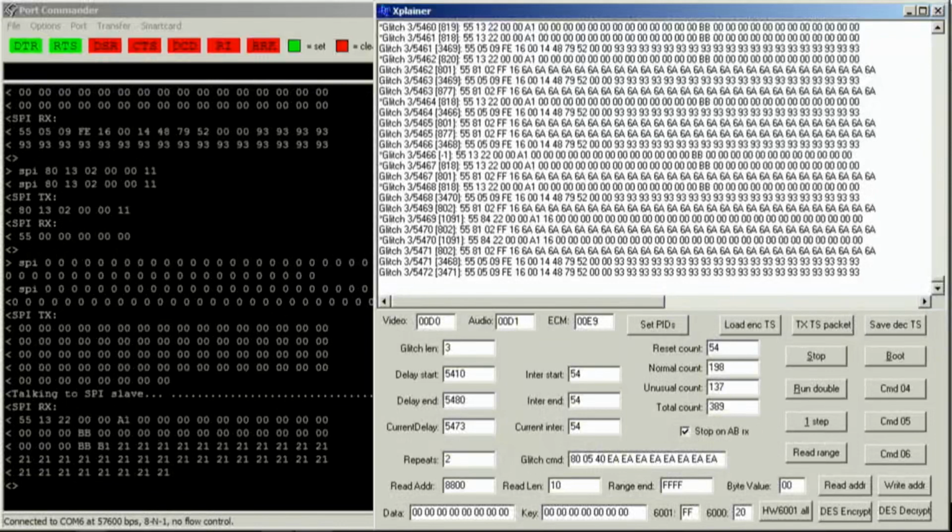There are specific addresses within RAM that can't be read, or the chip will lock up. These are clever traps put in as a safety measure. The 7-byte, 56-bit keys stored in RAM straddle these dead addresses. So any potential exploit that could cause a linear dump of memory will be stopped before you can even read a complete key. When the chip is reset, this means that I have to glitch in again because my code payload exists only in RAM and there really is no way to hook in any kind of permanent backdoor.